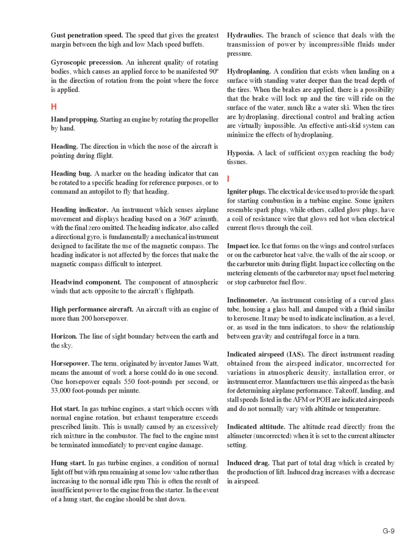Impact ice. Ice that forms on the wings and control surfaces or on the carburetor heat valve, the walls of the air scoop, or the carburetor units during flight. Impact ice collecting on the metering elements of the carburetor may upset fuel metering or stop carburetor fuel flow.